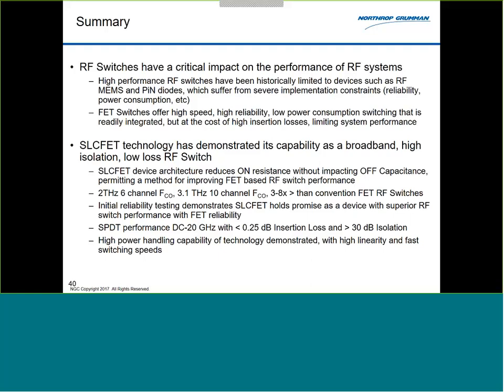The series device on that is I think 225 microns, which means, doing some public math, that's around half an amp. Obviously you can make it bigger, but if you make it bigger, then you start playing with what frequency regime it can operate in. But essentially, 2 amps per millimeter is the scaled number for our 6-channel. For the 10-channel, that's 3 amps per millimeter.